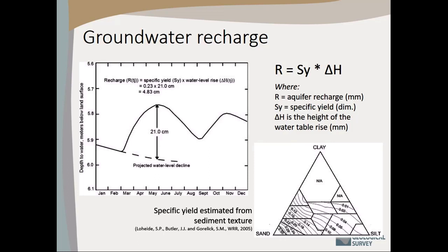That seems a little bit confusing to me in that I think about, from the water table as you go above it, the matrix potential is not constant, that it's decreasing as you go above it, and that the air-filled porosity or the drainable porosity would vary with elevation, not just with the texture value. So it seems like there's a simplification in the assumption.